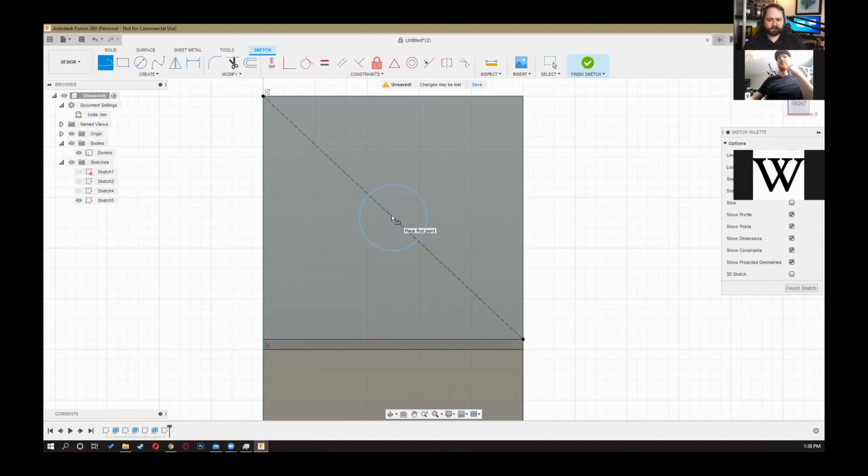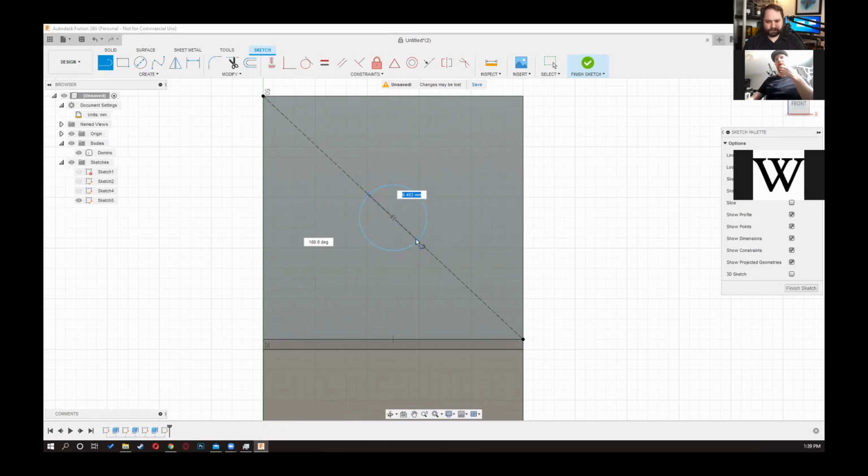So you're going to want to basically go over to your line type on the right hand side at this moment, and you're going to see at the very top, so click on that one. Yep, and now you're going to be drawing a non-construction line. You're going to go to where your construction line and the circumference of your circle meet, just on the outer portion of the circle, and drag it across following the construction line. Yeah, and then you'll see you have perfectly done that.